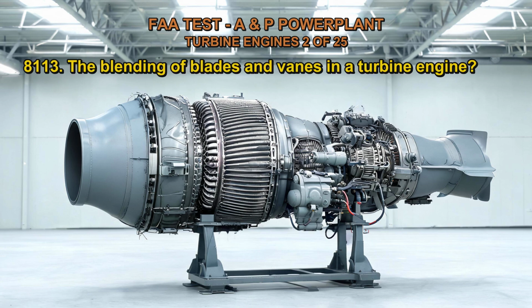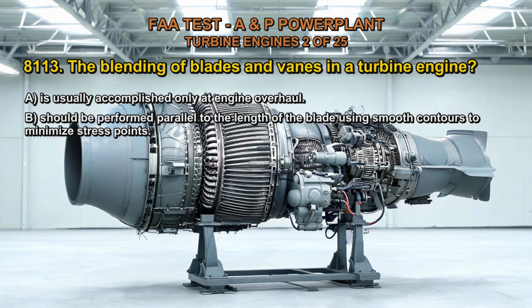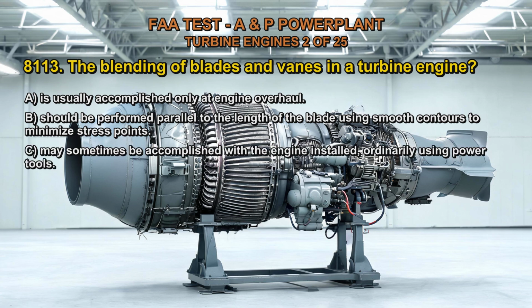Q8113. The blending of blades and vanes in a turbine engine. A. Is usually accomplished only at engine overhaul. B. Should be performed parallel to the length of the blade using smooth contours to minimize stress points. C. May sometimes be accomplished with the engine installed, ordinarily using power tools.